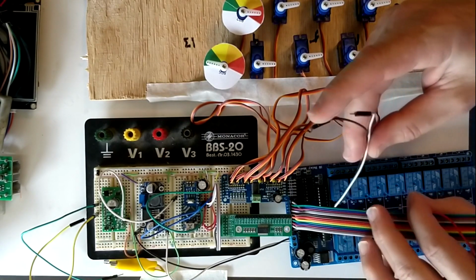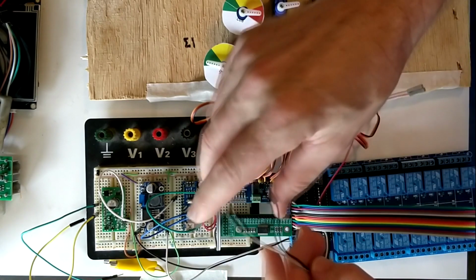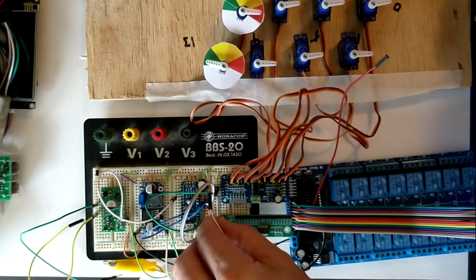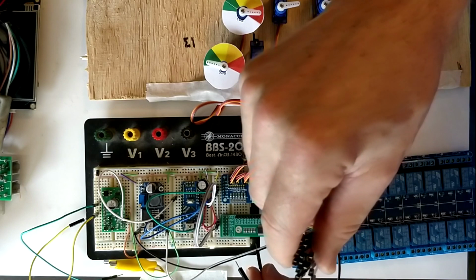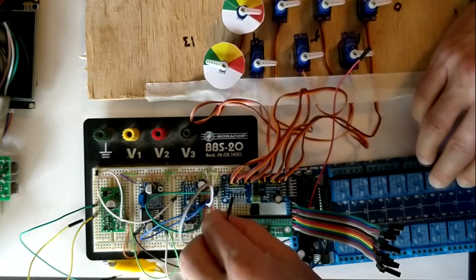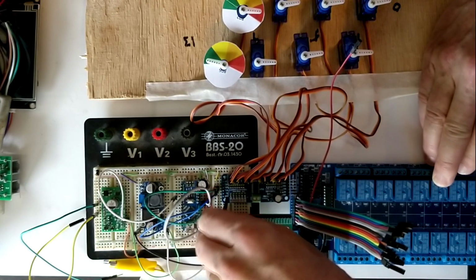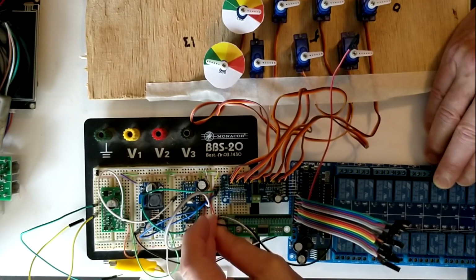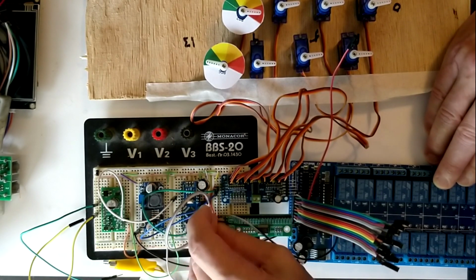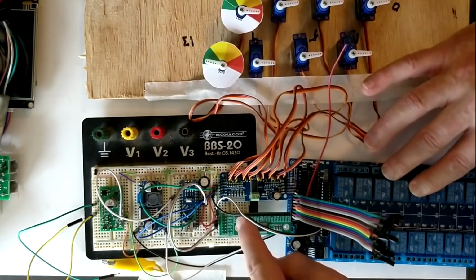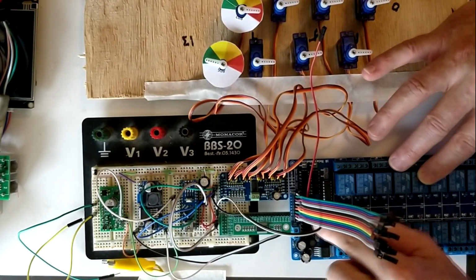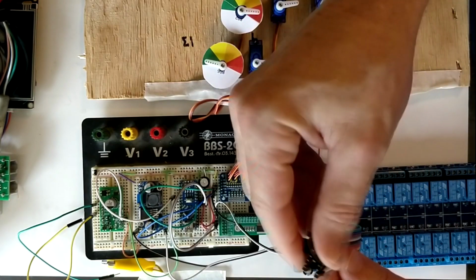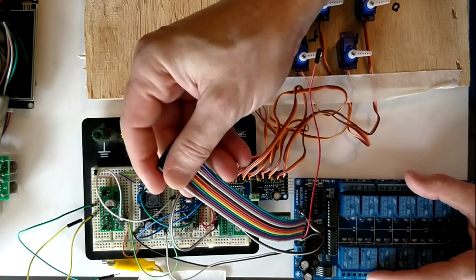And then I need 5 volt and ground, which I can connect to the 5 volts here on the Arduino. Now I just need to make sure actually the white one is 5 volt right here, and the ground actually goes right next to it here, to the ground connector. That's the black. Okay, black is ground, goes to the ground connector on the relay board. Okay, that's it. Now the only thing I need to connect are my 16 IO port lines.